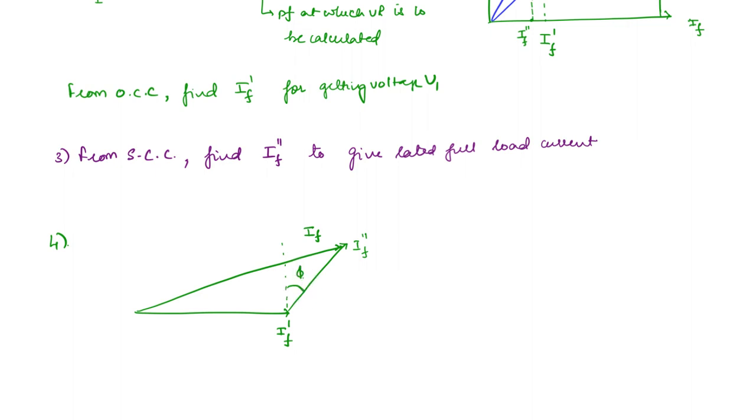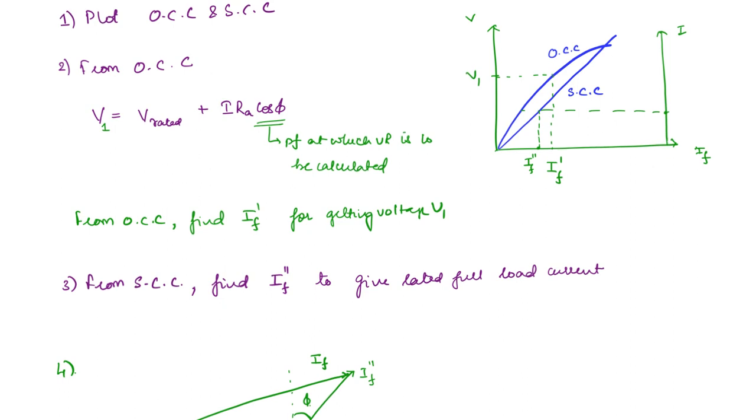So in the graph, once again, you will find out the open circuit voltage for this particular field current. Once we find out the open circuit voltage for this particular field current, then we can find the voltage regulation. Let us take this voltage to be EG.